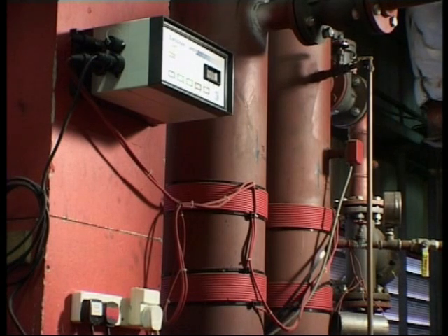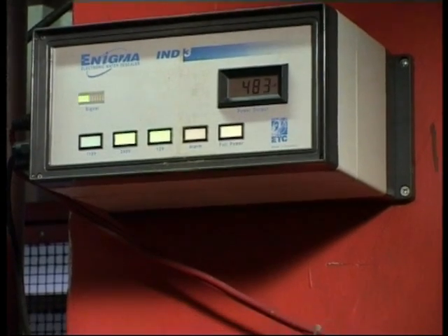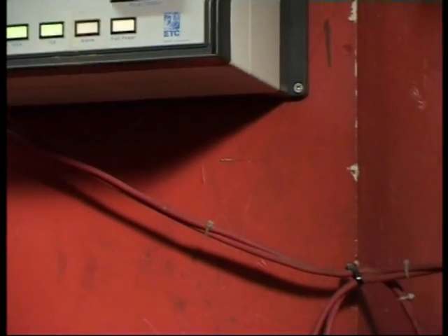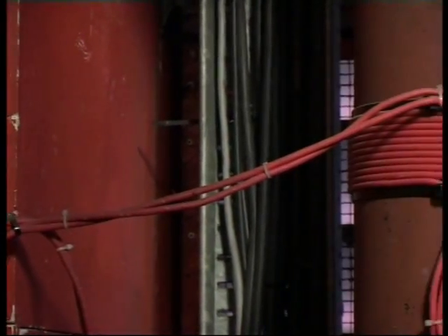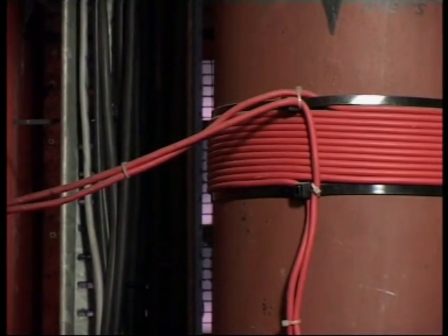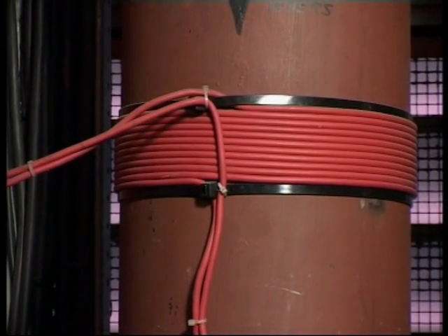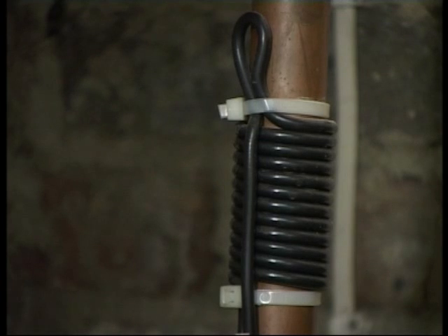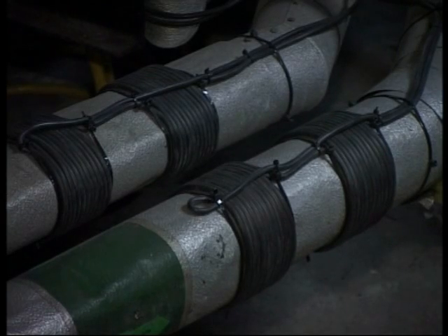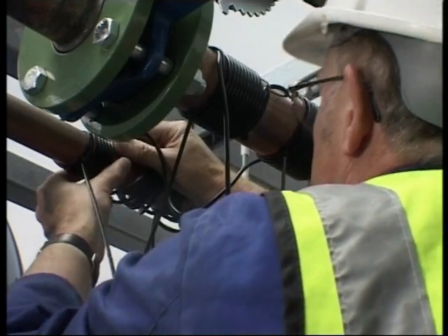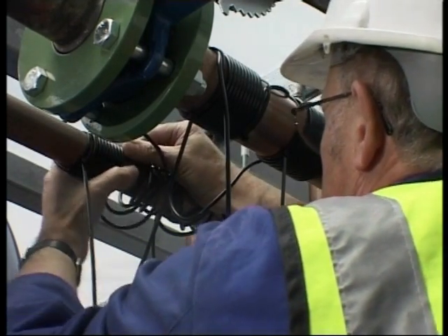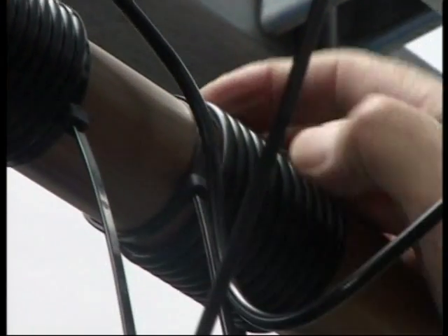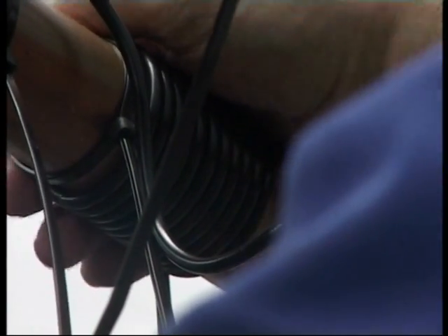The Scale Watcher ENiGMA is comprised of 2 components. The electronic unit attaches to the wall and is connected to the signal cable which wraps around the pipe feeding the system to be treated. A range of units are available to cover pipes of any material and size from 8 to 1250 millimeters. The application of a descaler involves no cutting or extra plumbing, but is simply applied by wrapping the signal cable around the outside of the pipe to form a coil.